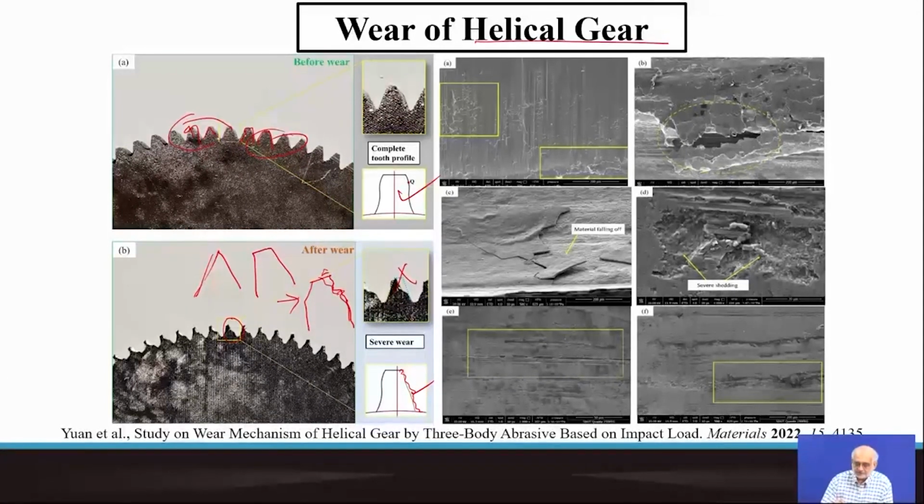So in order to ensure that no such damage occurs, we would like to create a certain compound layer on the surface, which will give this protection. We have seen how this can be done by either gas nitriding or liquid bath nitriding.